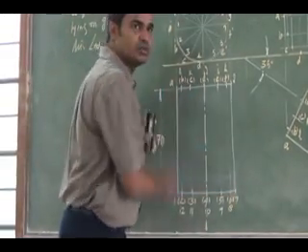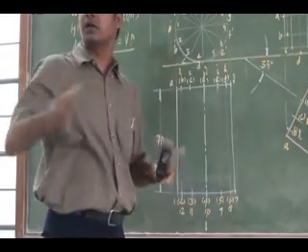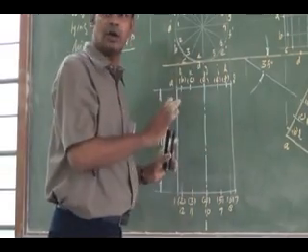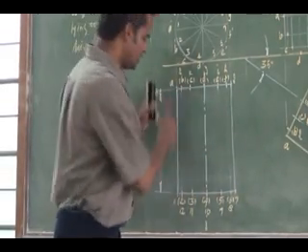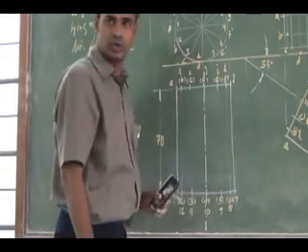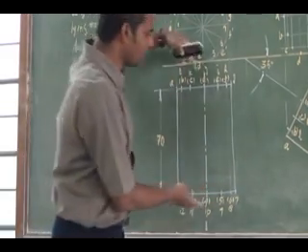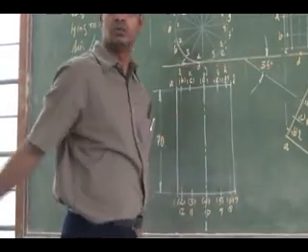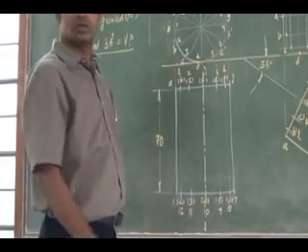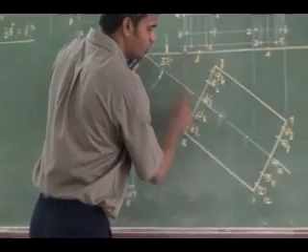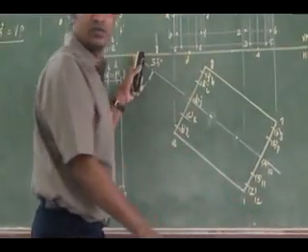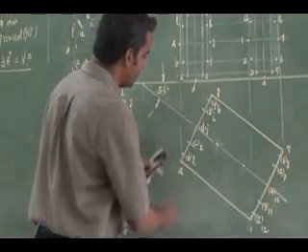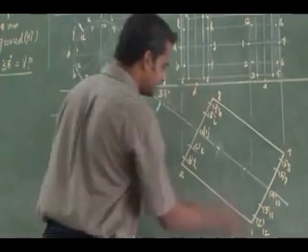Only the extreme generators should be visible in any view for a cylinder or cone. The cylinder can be seen as a rectangle alone in the top view. So show the rectangle, then the axis, then mark the hidden corners. Now I am going to tilt this simple-position top view to 35 degrees, that is, the axis inclined to VP at 35 degrees. Draw the axis at a 35 degree inclination from the reference line, below the reference line. Then I have redrawn this and drawn the axis.